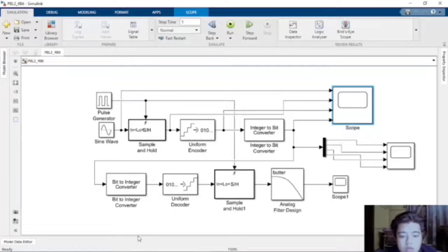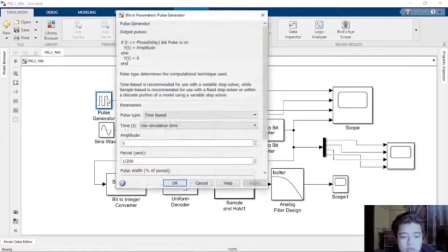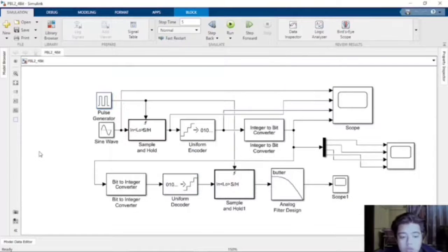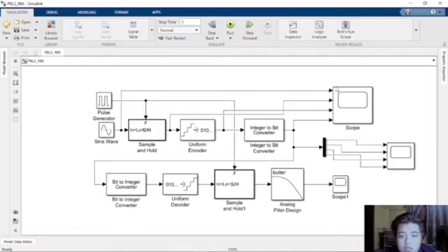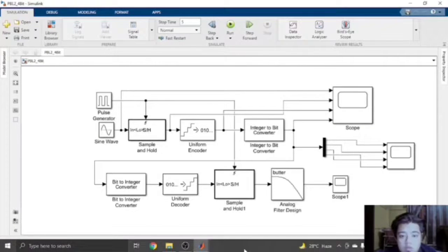In this presentation, we present the simulation for part A. This is a simulating circuit for 4-bit encoded PCM data. The sampling frequency in part A has been set to 200 Hz, which satisfies the criteria set by this project, which is to use 2 fm for the sampling frequency in scenario 1 and scenario 2. It will generate the PCM data at 200 Hz and 4 bits per sample. After assembling all this, we can run it to get the signal waveform.